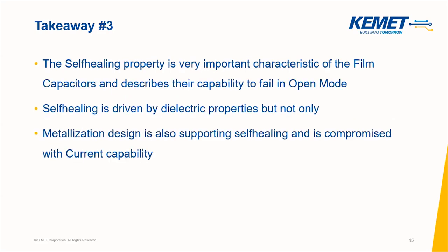We also had an overview of the most important characteristic of the film capacitor, which is the self-healing. We said that the self-healing is driven not only by the chemical characteristics of the dielectric, but also by the metallization. And the metallization is always a compromise between the possibility of carrying high current and good self-healing.